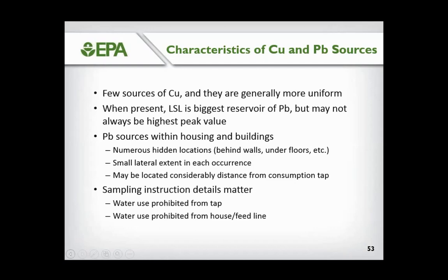The lead sources within the houses and buildings are numerous hidden locations, a lot of small laterals. They may be located considerable distance from the consumption tap, yet they can contribute to the lead levels. And sampling instruction details matter. If you tell a consumer or residents to not use water from that specific tap to be sampled, it is not the same thing as telling them not to use water from the house or the whole line that feeds that tap, because the first can result in a liter encompassing fresh water, whereas the second one will